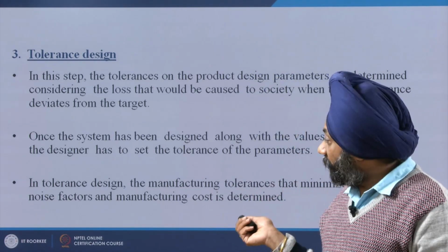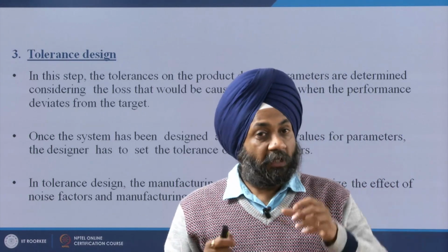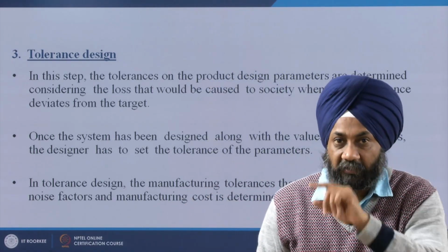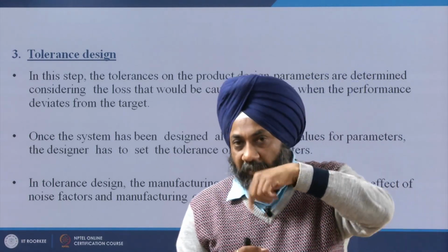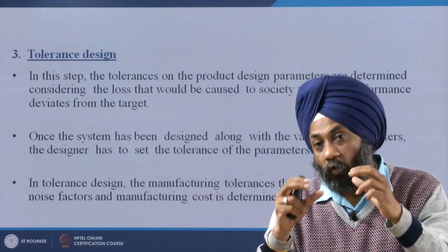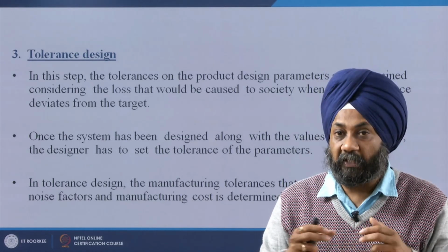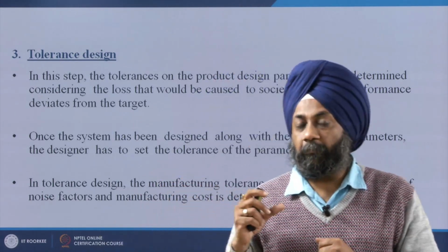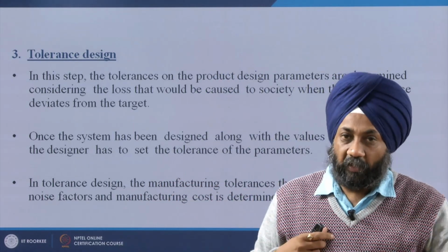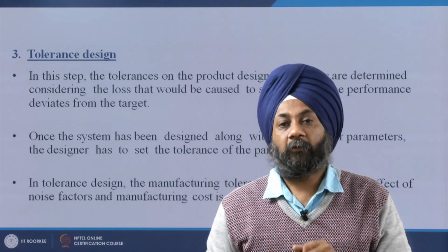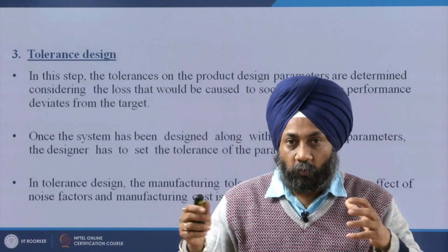Second, at the tolerance design stage, we have to see that when the bottle has to be closed by the cap, the threads inside the cap and on the outer periphery of the bottle are consistent with each other and follow the concept of interchangeability, which means that any sample of the bottle and any sample of the caps should be able to be assembled to each other. So that is the concept of interchangeability.